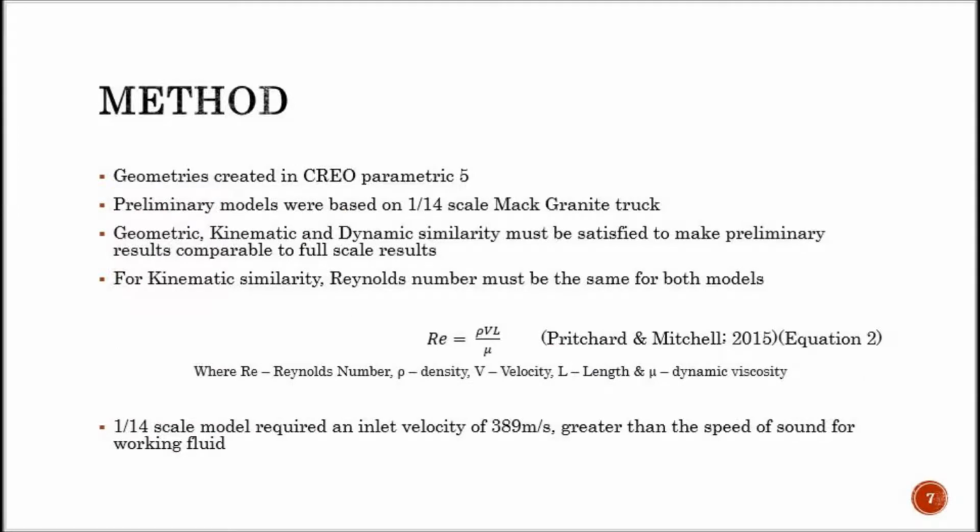The required geometries were generated in Creo Parametric 5. The baseline truck CAD model was generated using photographs and measurements made from a 1/14 scale Mack Granite semi-trailer truck. Using the 1/14 scale CAD model, preliminary studies into the airflow over this truck were conducted.